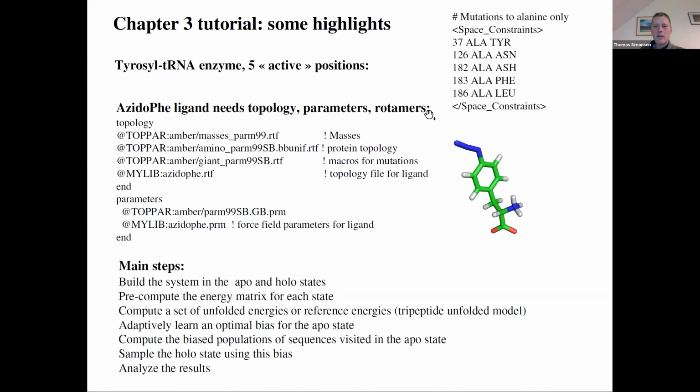Now, rotamers are the simplest because for Proteus, ligand rotamers are just poses. So you simply come to Proteus bringing your set of poses, each in its own PDB file, or grouped in a single PDB file, also fine. Ligand rotamers are just poses, and it's your job to bring those poses to Proteus. Proteus will not produce poses or rotamers for your ligand. That's upfront. You run AutoDock, whatever.